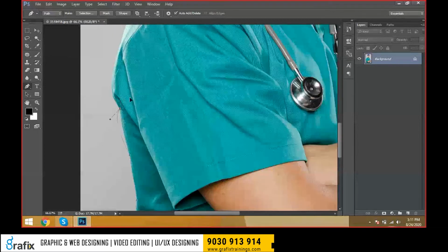Just click the starting point, this one, keep the pointer on the edge and drag it. Then automatically you can see the beziers like this. Now you can hold Alt and click the pointer. We can cut one pointer, then automatically we can continue the points.